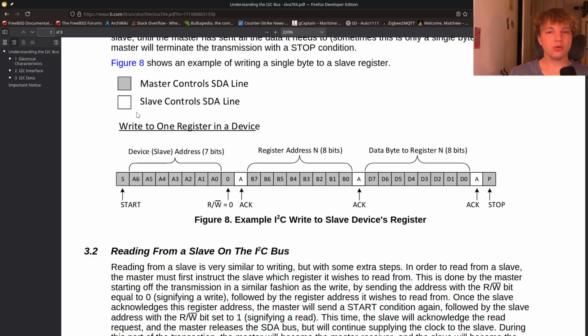So why would you not want to use I2C then? It sounds fantastic. Well, it's actually kind of slow. You'll notice here there's a lot more baked into the protocol, and there's acknowledgements that need to be sent. It's a courtship type thing, it's an entire transaction. It's a big deal. Whereas with SPI, you just go boom, boom, boom, data. There's a whole process we have to go through here, and that inherently makes it slower.